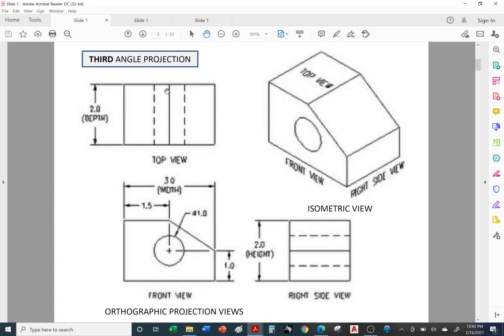They're called hidden lines. And always note that they line up with the quadrants of the circle, just like on the right side view. I did not mention this earlier, but here we go. We have the dashed lines lining up with the top quadrant of the hole and the bottom quadrant of the hole.